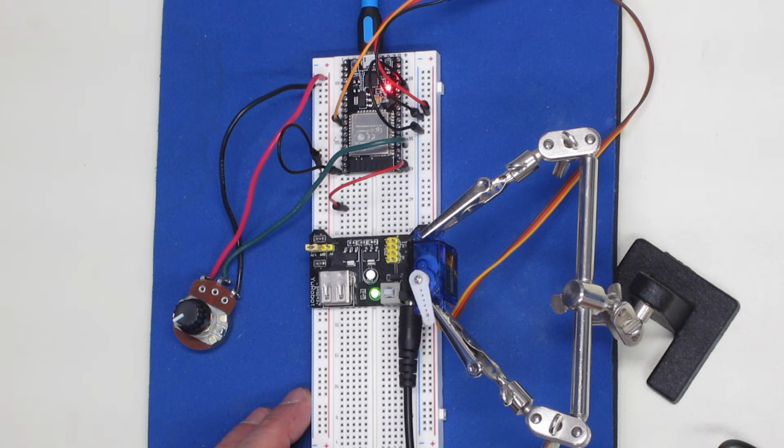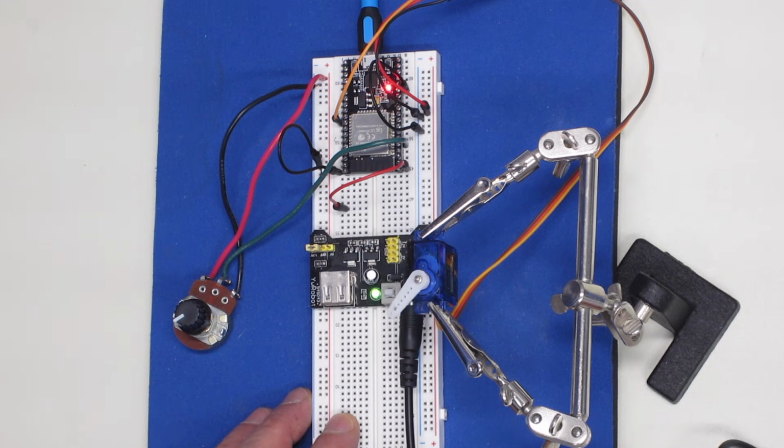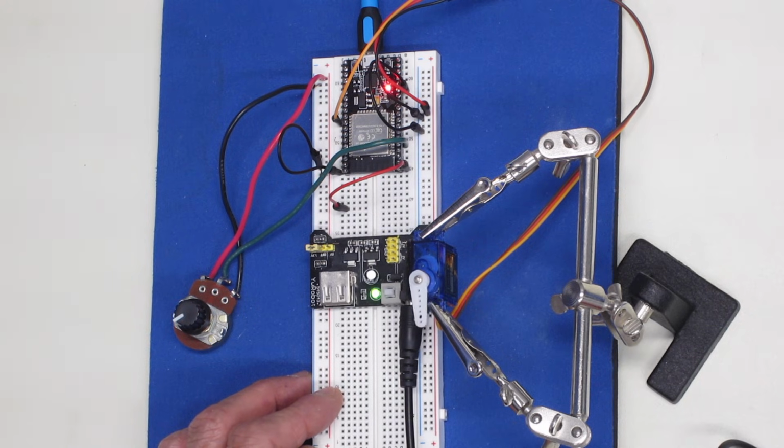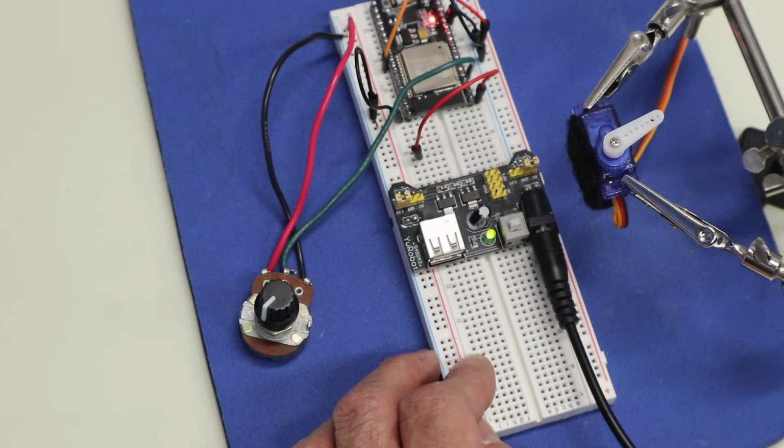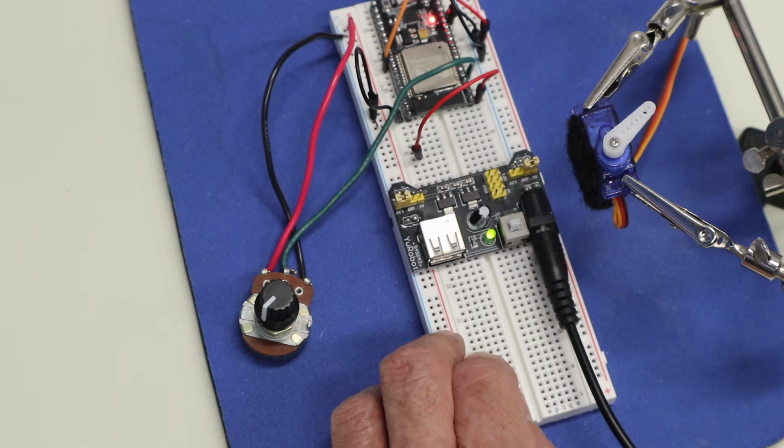And of course, you can fine-tune those parameters for your servo motor to get an exact 180 degree turn over here. And every servo motor will be a little different. Even two servo motors of the same model number can require slight adjustments. And by being able to do this, you can actually get some very accurate positioning using this code. So now that we've seen this, let's go and move on to another code example.